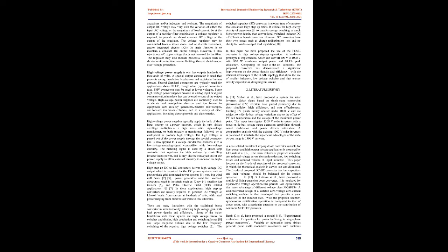Rectifier is a device, which converts the sinusoidal AC voltage into either positive or negative pulsating DC. PN junction diodes can be used for rectification, i.e. for conversion of AC into DC. The rectifier typically needs 1, 2, or 4 diodes. Rectifiers may be either half-wave rectifiers or full-wave rectifiers, center tap or bridge type.